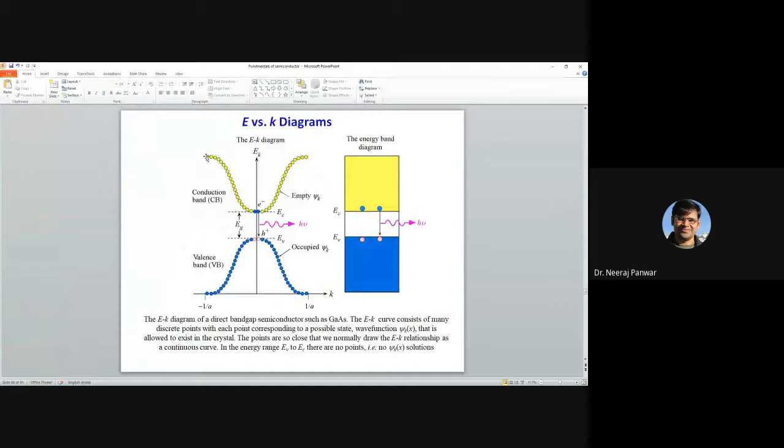semiconductors. So this is a particular E-k diagram for a semiconductor. And for a free electron, it should have been a perfect parabola. But as we study in the condensed matter physics course, the electron in a semiconductor is not as free as we think. So its behavior, the E-k diagram, is not completely a parabola. It deviates from the parabola, and you see the curvature. How it is here. It is upward, and here it is downward.